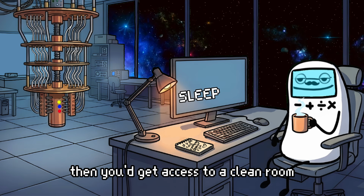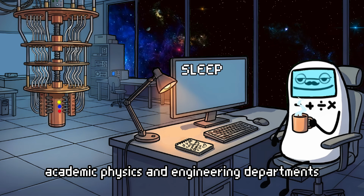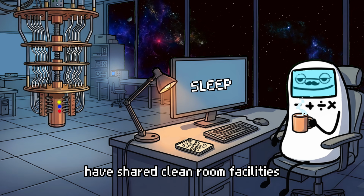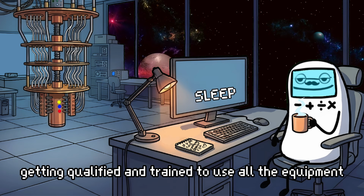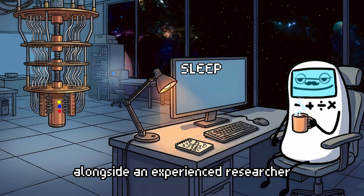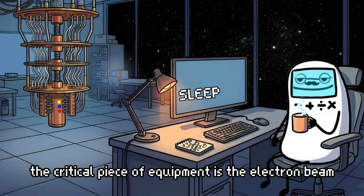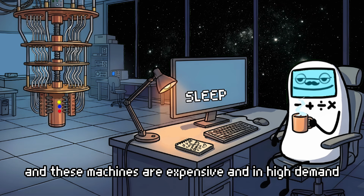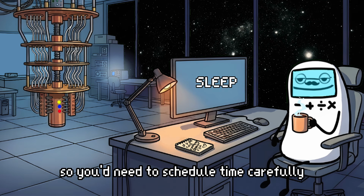Then you'd get access to a clean room. Academic physics and engineering departments at research universities have shared clean room facilities that qualified researchers can use. Getting qualified and trained to use all the equipment might take months of work alongside an experienced researcher. The critical piece of equipment is the electron beam lithography system for making the Josephson junctions, and these machines are expensive and in high demand, so you'd need to schedule time carefully.